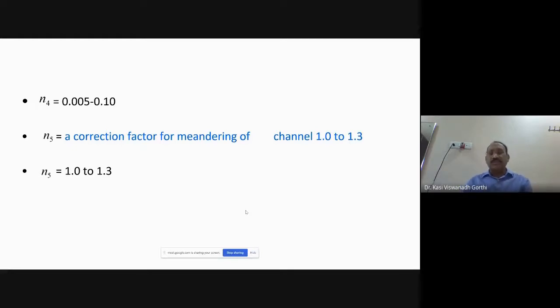Okay, so today's class, we have seen about the uniform flow. What are the main features of the uniform flow? Starting from the simple definition of a uniform flow where the depth of flow remains constant along the channel direction. So Y1 would be equal to Y2. Since Y1 is equal to Y2 for a prismatic channel, A1 will be equal to A2. And the discharge equation and the continuity equation Q is equal to A1 V1 is equal to A2 V2. Hence, the velocity V1 also would be equal to V2.